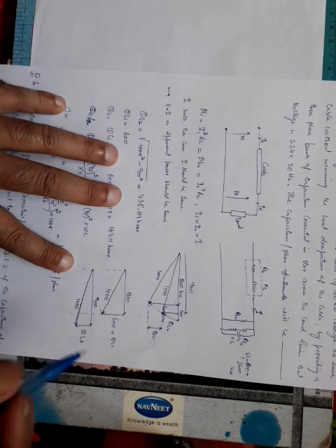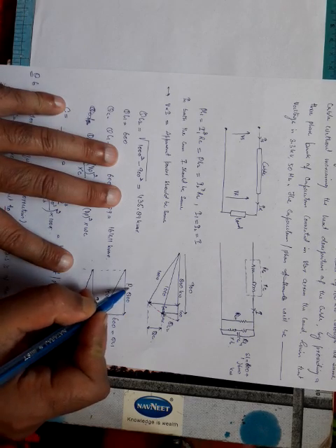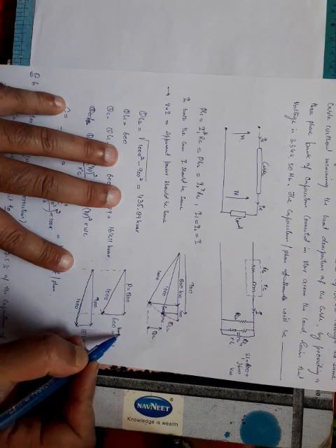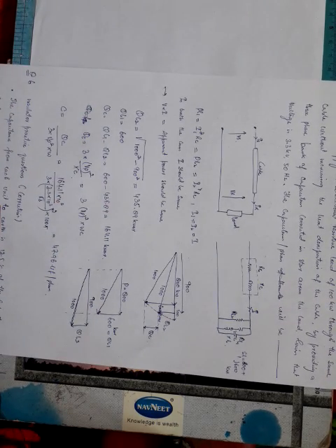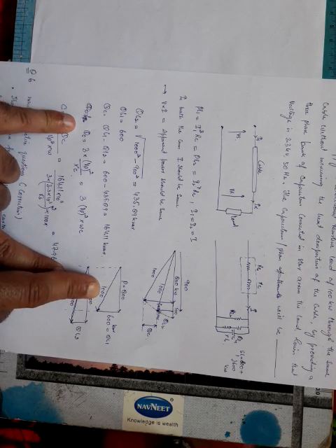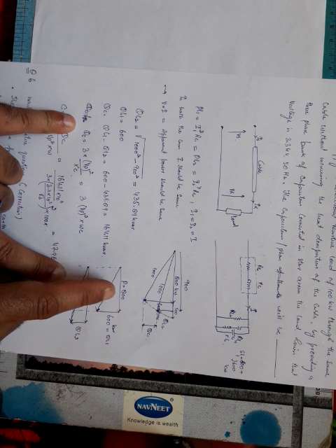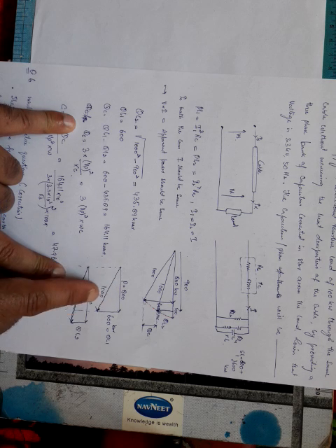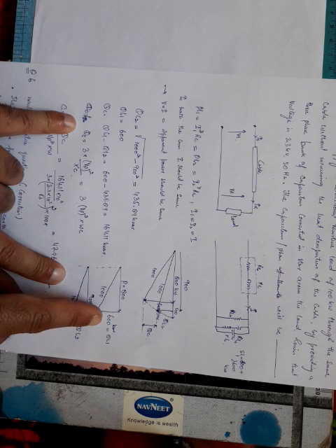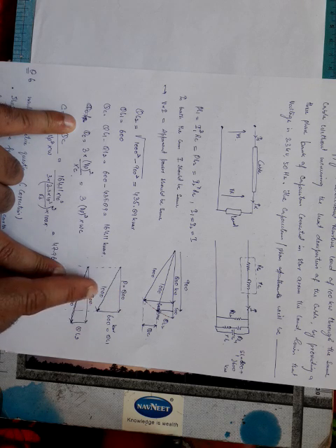This is the 800 kilowatt, that is P, and this is 600 kVAr, that is Q. It is given in the question that the load is inductive. The power triangle for the first case is this triangle. By squaring and adding these two, because this is a right angle triangle, the square root of 800 square plus 600 square gives us 1000.